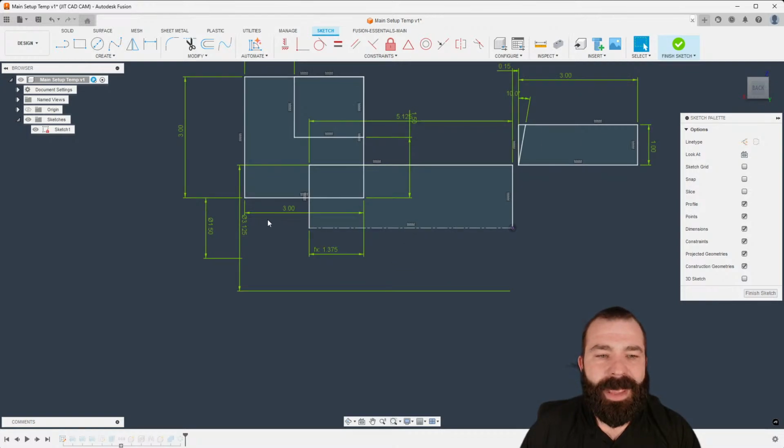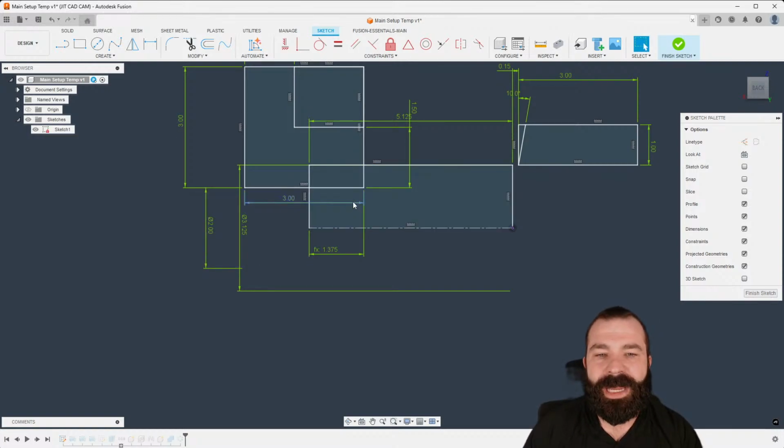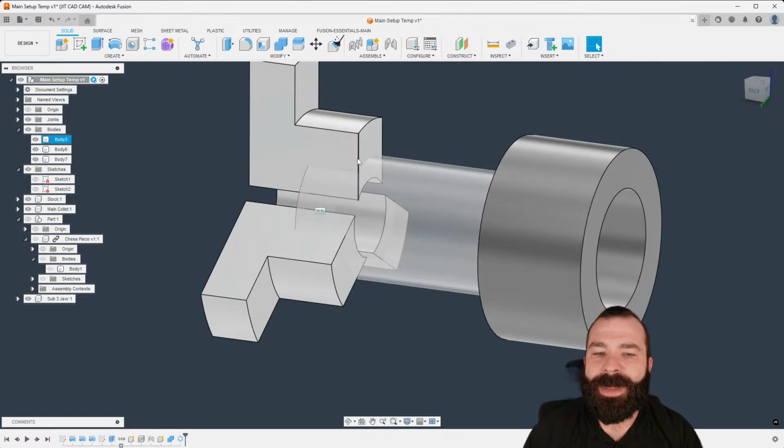But again, as you all are seeing here, we're going to make a few more adjustments because I'm going to grab a little further out. Let's say we actually want a 2-inch diameter with that soft jaw. Adjusting my sketch will automatically move my jaws outwards, because of the way the timeline works, everything else is in place.